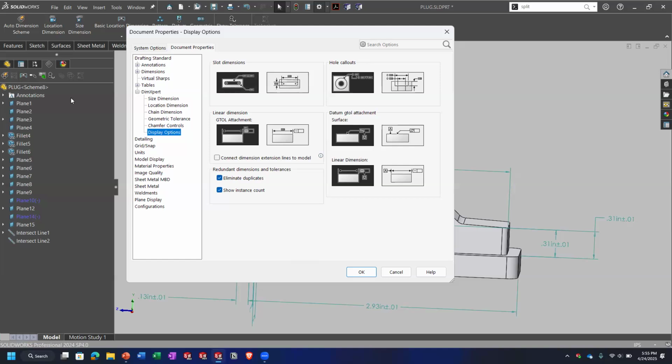What I did isn't the dimensions that I modeled to. Those are just dimensions based on the datums. Now, if you modeled to your datums, then in theory, those are the dimensions that you modeled to, and they are already there. You could just show those dimensions instead of creating new dimensions, but you don't get some of the other benefits of DimXpert. So still quickly going through and adding them into DimXpert does give you additional benefits. And I'll show you how to incorporate that onto the drawing in a second.